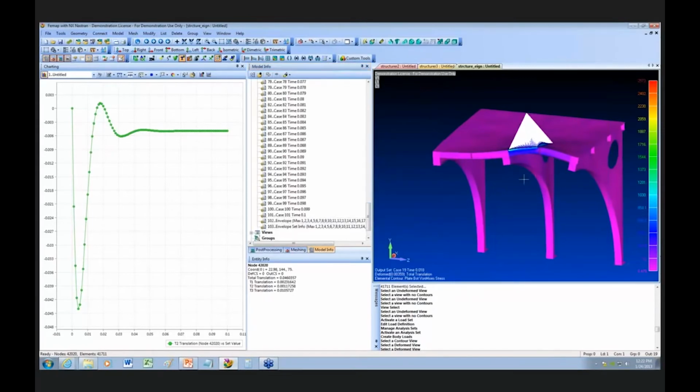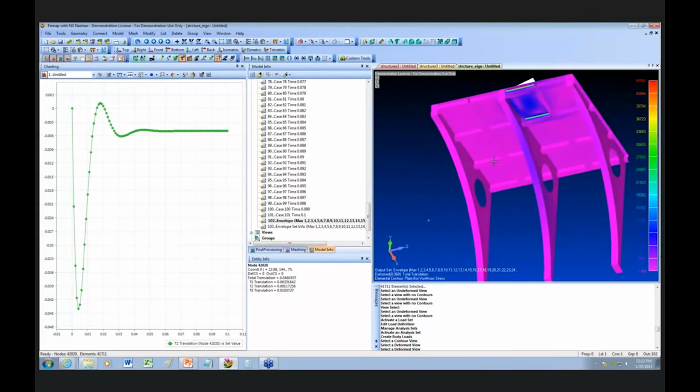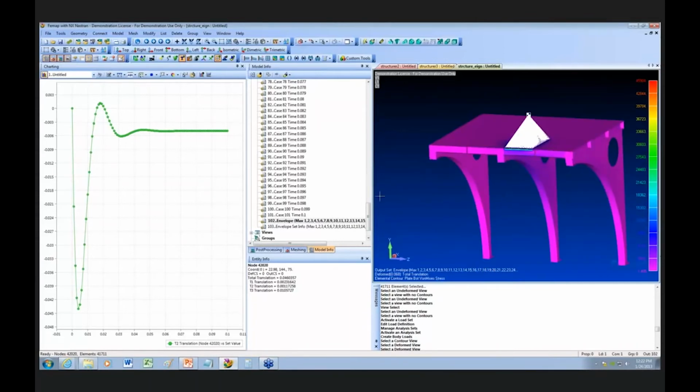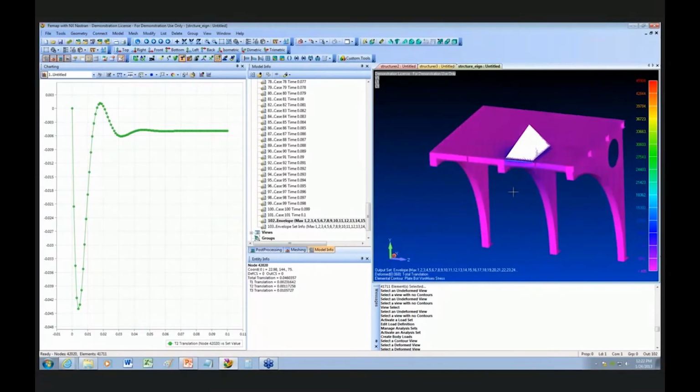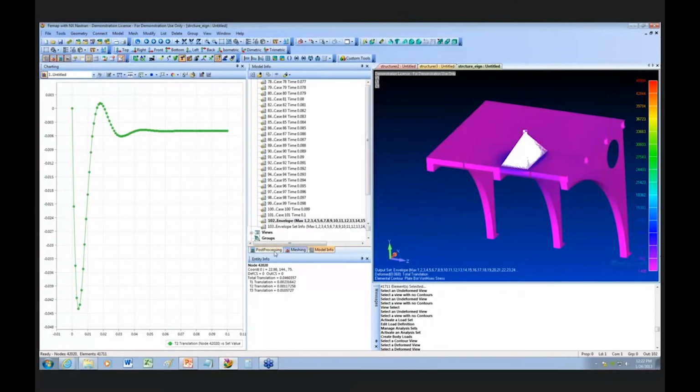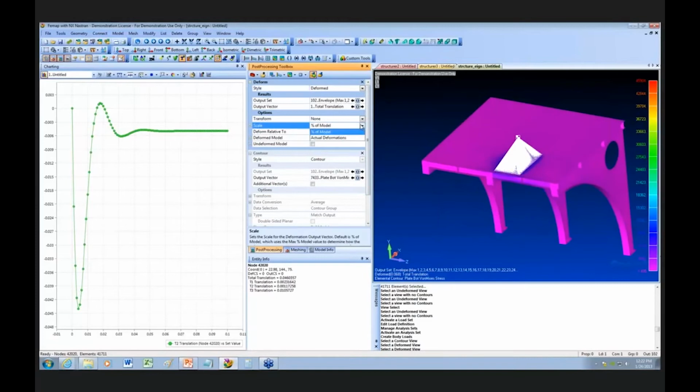I've already run it. It takes a couple of minutes, maybe 3-4 minutes, to go through all these stresses. And again, I'm looking at von Mises stress here, so I ask for the maximum. And so what I can do is come down here and click on this, and I can see the maximum stresses here. And if I want to really find out if I have exceeded the yield, or how much I've exceeded the yield, I can come over here to my post-processing toolbox, and I do have the deformation turned on, but I probably need to turn up a higher percentage of the model, but that's not important here.